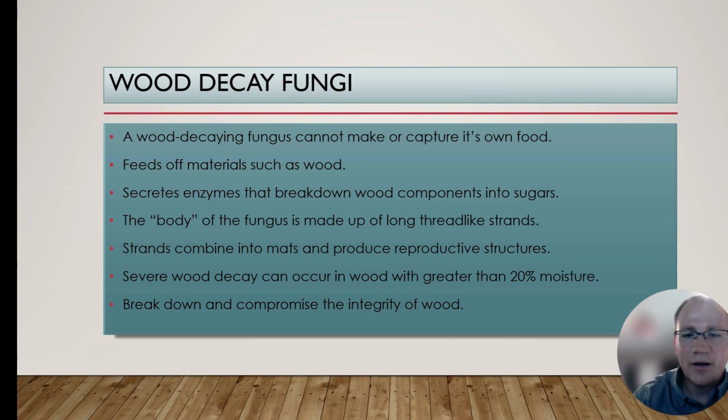Severe wood decay can occur in wood with greater than 20% moisture. These are going to break down and compromise the integrity of the wood. So once again, people are definitely concerned about the respiratory issues we talked about in the last slide, but they're going to be even more concerned when you're breaking down the structural integrity of their wood. So you really need to do a good inspection when it's coming to something like this because structural issues are going to be a big deal.